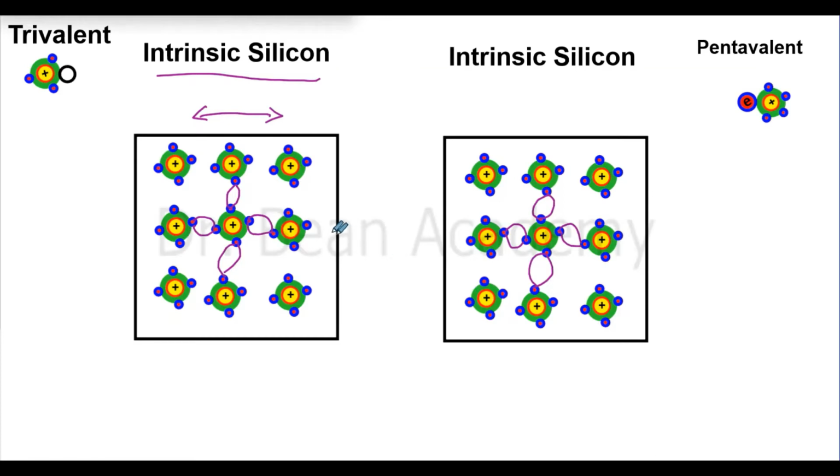In this situation, silicon behaves almost like an insulator, because all the electrons are engaged in covalent bonding. And once they are bonded, it's not easy to force them to flow through the material or move, because it's not easy to snatch them. If an electron is in the valence shell, then it's a bit easy to snatch it from its nucleus, but now it is shared with another atom through a covalent bond. So this situation is very stable and it's not easy.